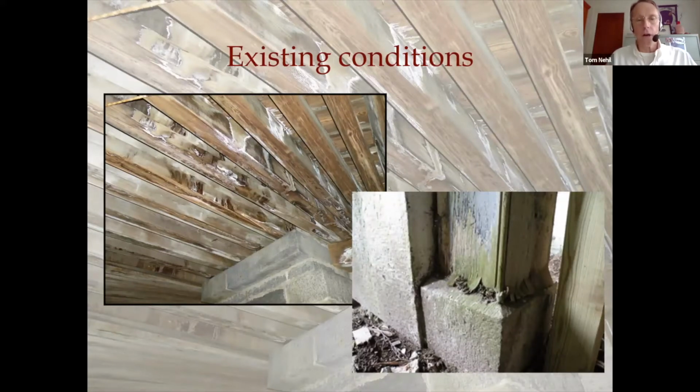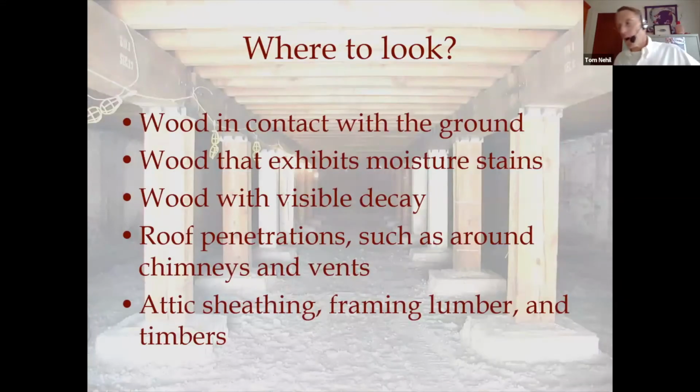Now, part of our job then is to sort out what looks kind of crummy from what is actually seriously damaged. And so water staining is not uncommon, but water staining may not be an indicator of actual damage. On the other hand, on the right, crushing at the bottom of a post, well, okay, something's gotten kind of wet and soft down there, hasn't it? And so we'll map out where we expect repairs to actually have to happen prior to even considering what's left.